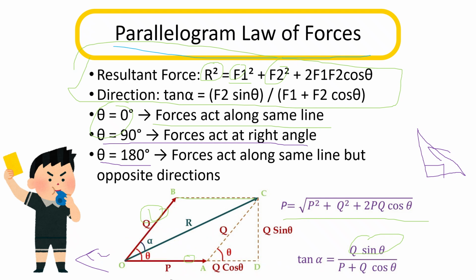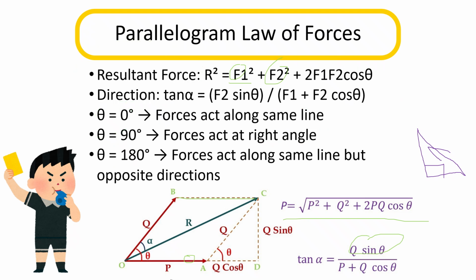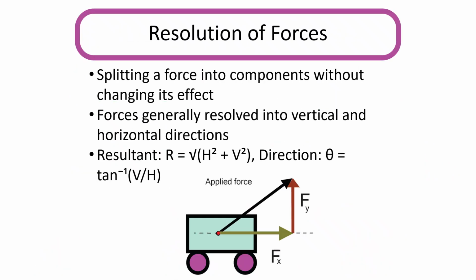What is acting, what are the forces, resolutions. Now the next thing is resolution of forces. How will you resolve the forces? To resolve the forces, you will have one single force. Suppose that this is my applied force acting along this way, and this is the theta angle. So in the y direction there will be Fy, and in the x direction there will be Fx.